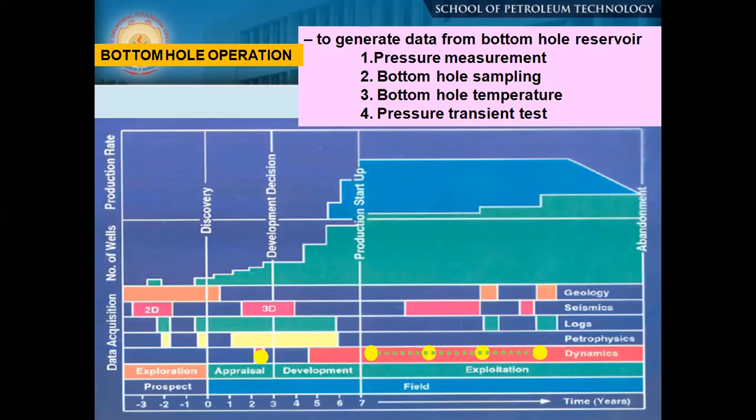I'm just saying this grossly, not going into the details. Then we perforate. Once we perforate, this well is activated. Either a stimulation or activation job has been done. Then this well is handed over to the bottom hole party, or you can say the reservoir people. Actually, this well test is generally done by the reservoir people in most cases.